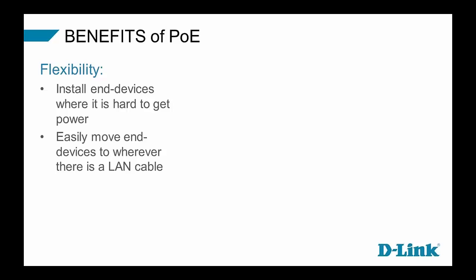With PoE, as long as I can reach it with a LAN cable, then I'm good to go. And I've got IT guys that run LAN cables all day, and it's pretty straightforward for them to get the LAN cables up there into the drop ceiling or wherever it is that I want to install my devices. And if I decide that camera's in the wrong place and I want to move it 20 feet to the left, as long as I can move my LAN cable, then it's pretty easy to relocate the device. And again, I don't have to call on an electrician to relocate an AC power drop.